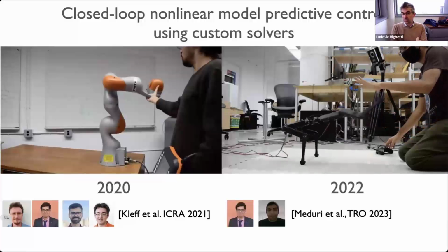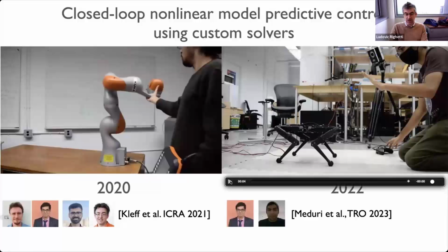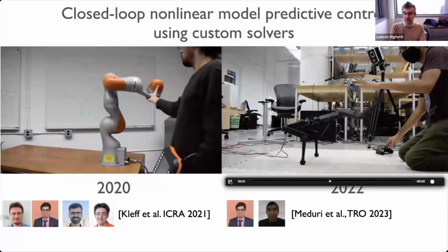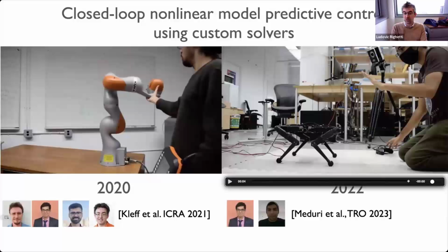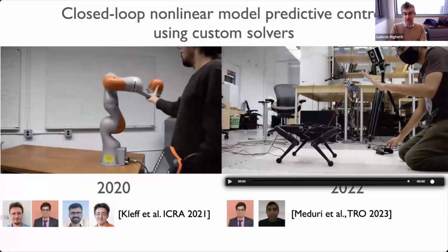The other thing, we designed some custom solvers for legged robots, so you can get robots to walk, to trot, and things like that. But what you can do is you can do anything, right? So you can ask the robot to reach a certain height, and on the fly you can generate a dynamically consistent trajectory. You can execute it on the fly on the robot, and you can do arbitrary movement, which is kind of nice.